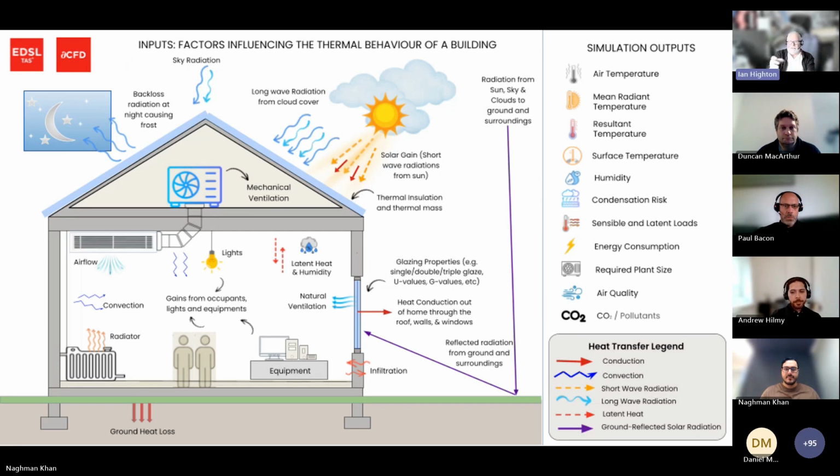Whereas the other gains, like the solar gain, wind speed and wind direction, these weather input parameters, they're all previous hour averages. People always ask, why do you have an hourly reporting interval? Well, what's the point of reporting sub-hourly when the input data is hourly fundamentally? That's what we're working off. Let's look at that now.